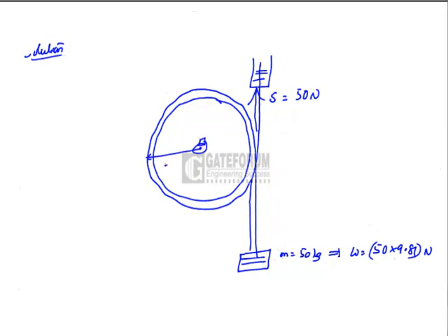The diameter of the drum is given as 700 mm. Therefore, radius is 350 mm. The rotational speed of the engine is given as 900 rpm, revolutions per minute. Now, first of all, let us calculate brake power in kilowatts by using the formula.